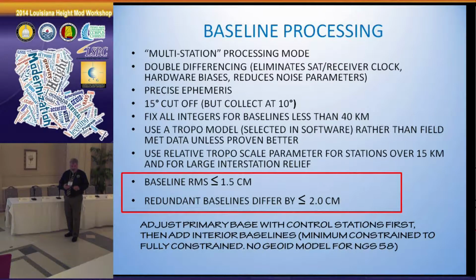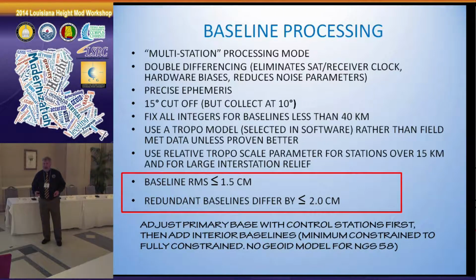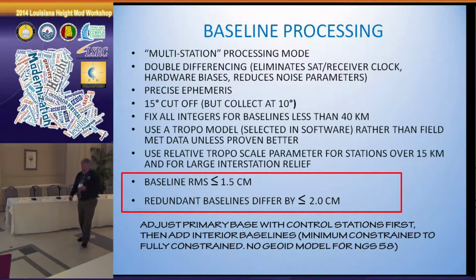And the thing here is, if you remember what I was saying before lunch, the ephemerides of the satellites tell you where they are exactly. The post-fit tells you where they really were. The broadcast is what they send you. And what these guidelines say is wait till you get the precise.